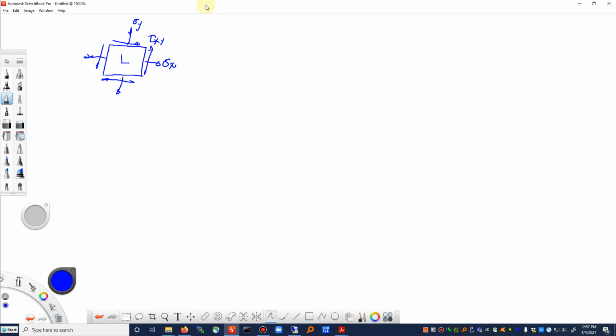There is some terminology that you should know that goes along with multiaxial stress states. And since we're talking about fatigue, all of these can be time histories of these different stress components. The first case is what is known as proportional loading or proportional stressing. Again, that's another term. I will almost always say proportional loading, and as far as the stress state goes, what is meant then is that we have proportional stressing.